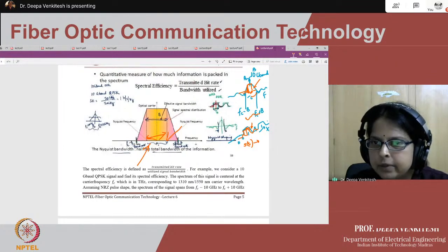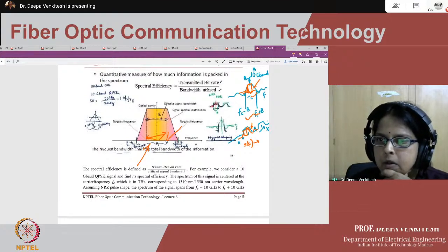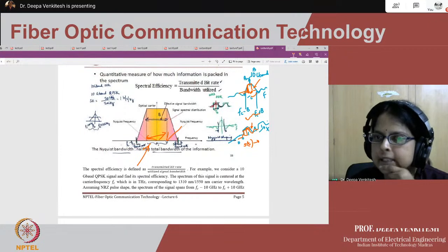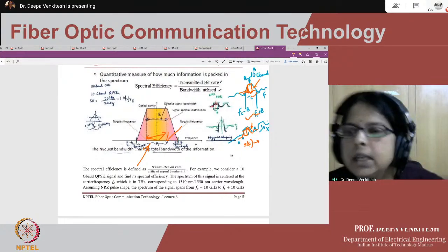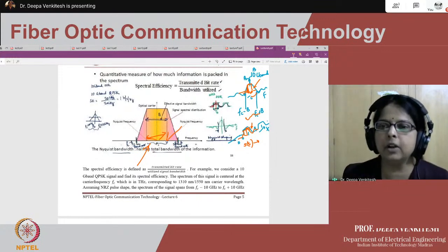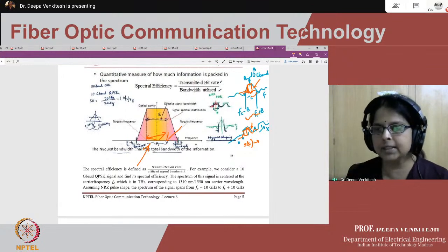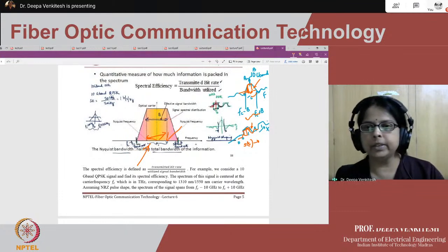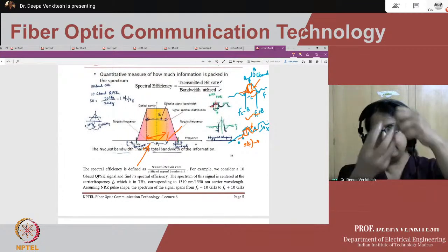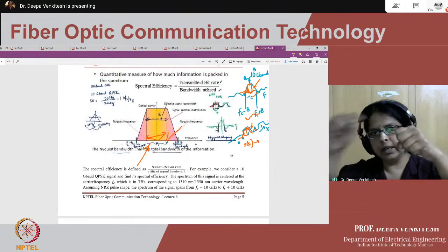So question from Arjun. The rate of non-radiative recombination depended on the quality of fabrication. Is it like if we reduce the number of defect states, we can get a better internal quantum efficiency? That is correct, Arjun. You see, first of all, why do you have non-radiative transitions, non-radiative recombination? Because these electrons, instead of coming directly and combining with a hole, are getting trapped in defect states.